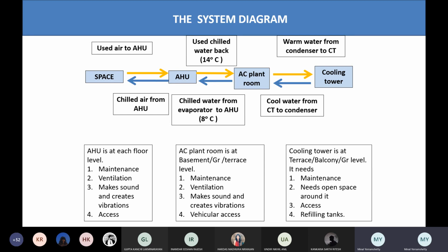Okay. So the terrace is a little dicey, unless it's a VRV system, because a VRV system comes in small slots and it can be joined and increased and decreased. That's why it's sustainable. Cooling tower is definitely at the terrace. The reason I have explained to you last time: it requires a blast of air going over it so that the water that trickles into that jali-like thing and collects into the tray before it comes down to the basement gets cooled, not chilled.